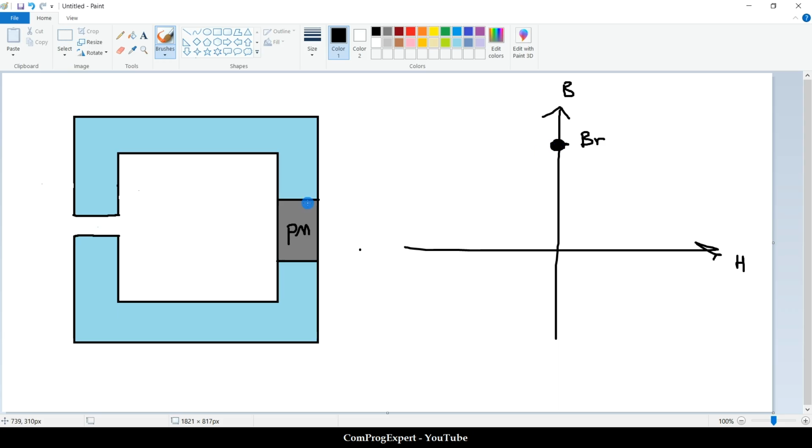So in this case, when we consider this air gap, how much will be the value of the B gap and H gap? Okay, so again, as I explained, this is ideal iron. So in this case, we can use the same equations that we have. Curl of H is equal to 0, this Maxwell equation. So integral of H dot dl is equal to 0.